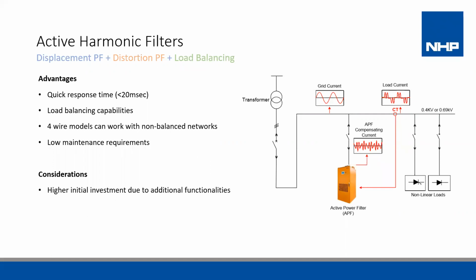However, you will need to consider higher initial investments, as this technology is typically more expensive than the previous technologies mentioned. But keep in mind that the APF can provide both displacement and distortion power factor correction and load balancing, essentially an all-in-one device.